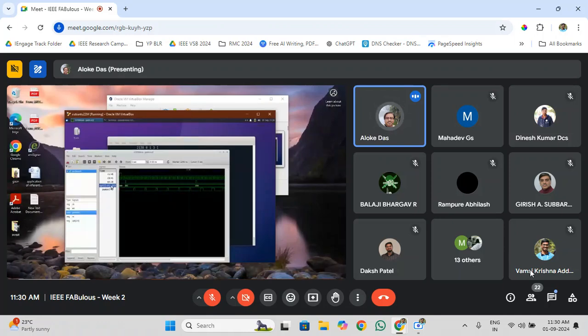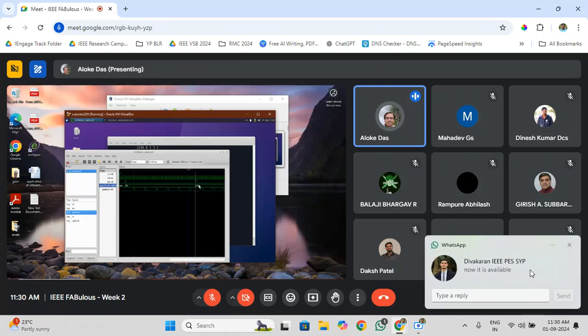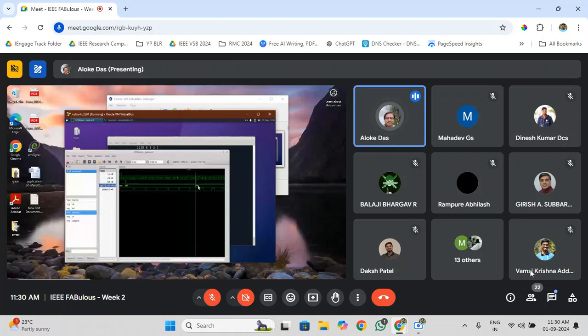What I was saying, so this enable signal, whenever enable is high, I can change the duty cycle value, and uptime is the register where I save this value. So here I made it 1. That means this PWM output will be 1, so it is up for 1 cycle only. Then again, after some time, I made it 2. I made the enable signal high and changed the value of the duty cycle. That means binary 10 means 2, it should be up for 2 cycles.